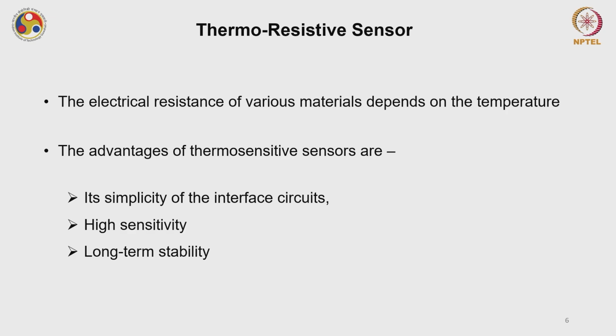However, the advantage of these thermoresistive sensors is that they are very simple. What you are doing is giving some temperature and its resistance is changing. Therefore, the interface circuit designed for these sensors is very simple. They have good, or decent, sensitivity in the desired temperature range.